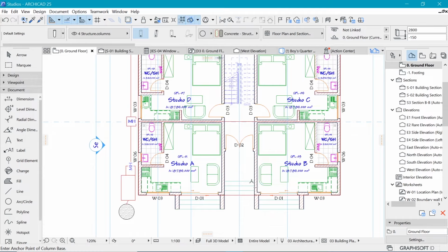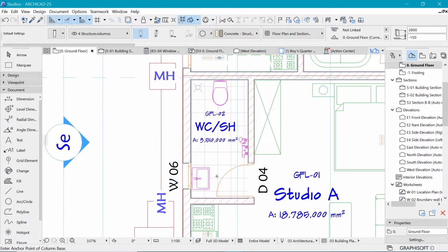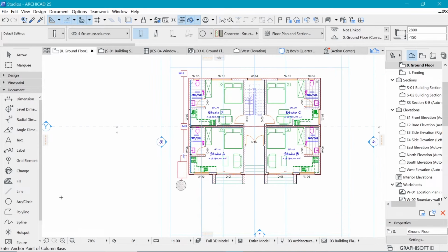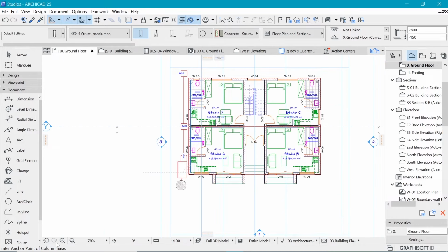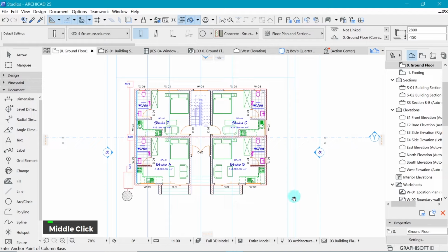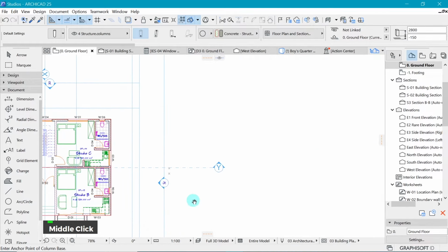And then next, in case you wanted to zoom into a particular section, we have a Quick Options bar along the bottom here. So you can click, for example, here and create like a section here, and Archicad can actually take you to that place. And if I zoom out as well, you can see we go back. So if I go Previous Zoom, it will take me to that. Go Next Zoom, we go back to where I had zoomed out to. If you hold down the middle mouse button, you can click and take yourself to the next part of this drawing.